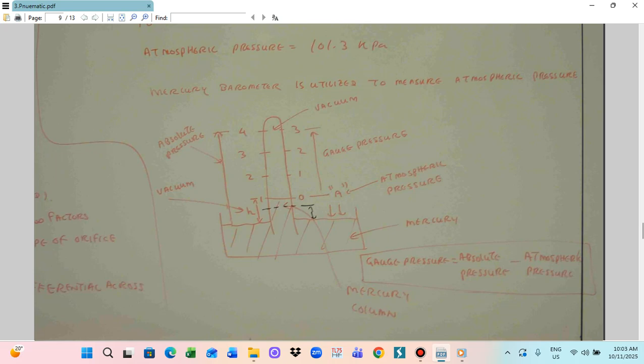So we have to measure the gauge. All the vacuum pressure must be less than the air pressure. After the vacuum is properly done, they can recharge the refrigerant. They charge the refrigerant and then measure again. After that they check for leakage, whether there is a leak or not.